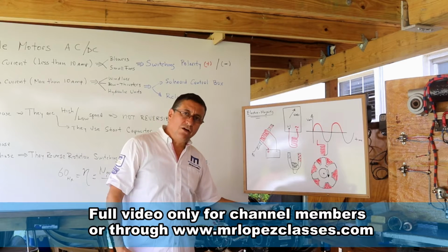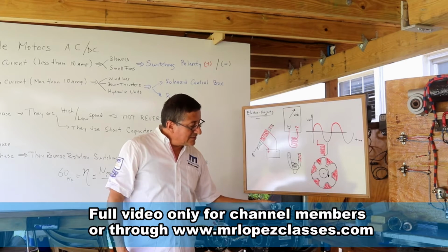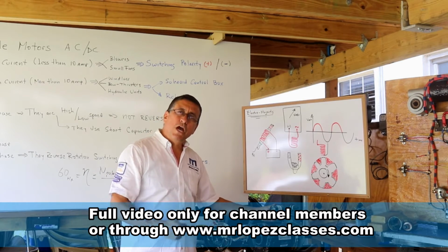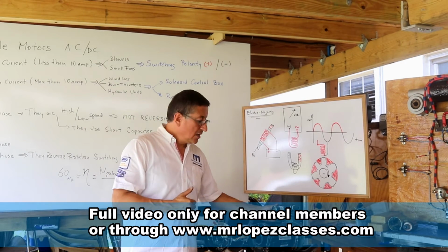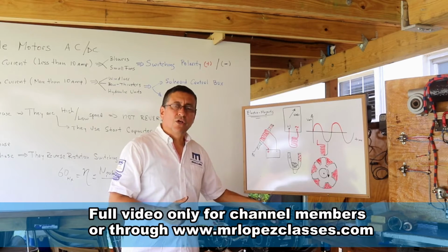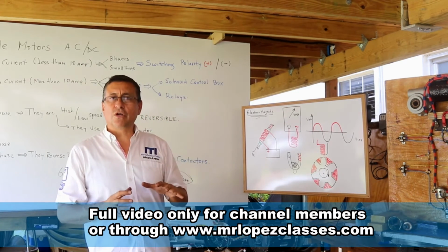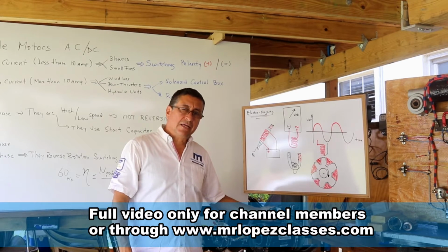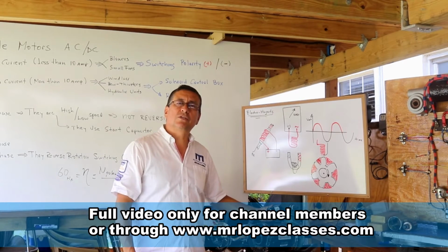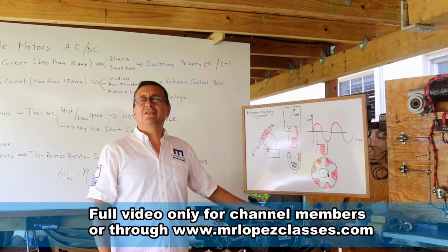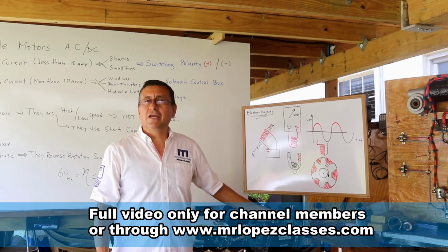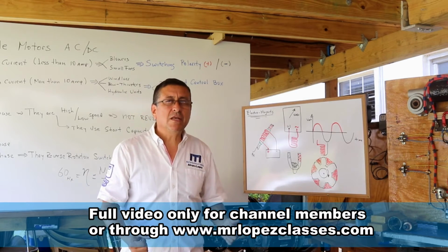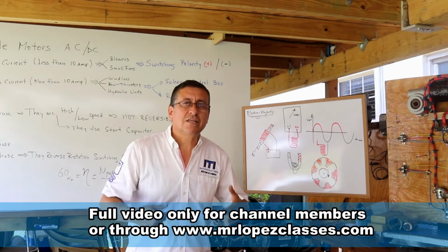This is the example. This motor is a single-phase motor, and this is the capacitor. The capacitor is used only at the beginning, to produce an extra voltage in order to start the motor. All the single-phase AC motors have a start capacitor, and the capacitor is used only to start. What is the symptom when the start capacitor in a motor is damaged? The symptom is that the motor is humming and it's difficult to start.